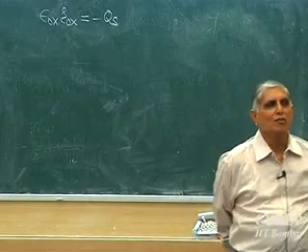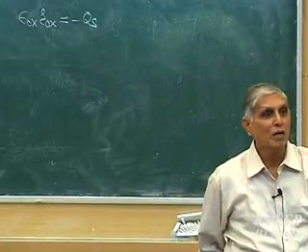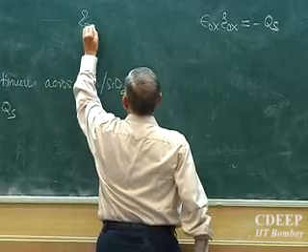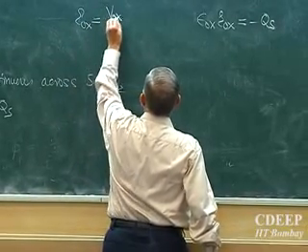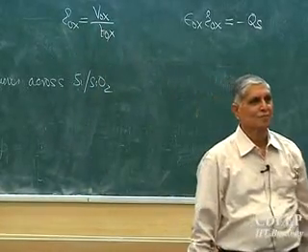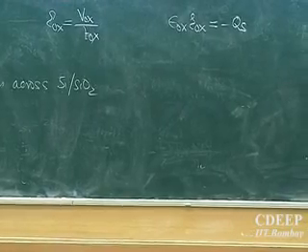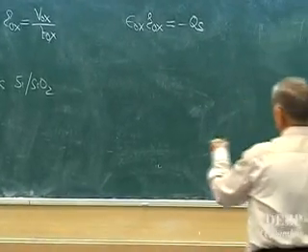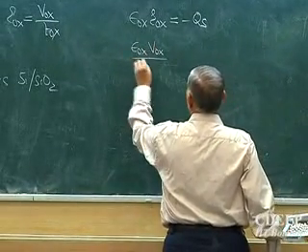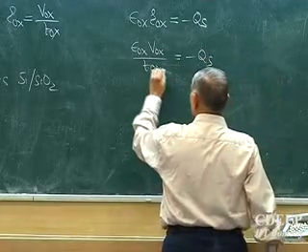However, what is the electric field in the oxide? Just see that figure. How much? Yeah, very good. The electric field in the oxide is nothing but voltage divided by thickness. Is that okay? Vox by Tox is the field in the oxide. I substitute it here. So I get epsilon ox Vox by Tox is minus QS. But what is this term?